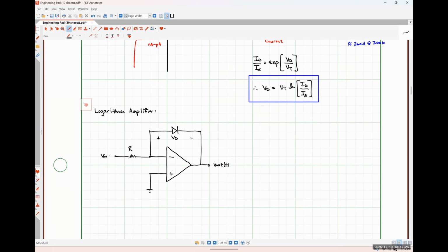Relays are inductors, and sometimes they will generate very, very large current or voltages if you turn them off really fast. So you put a flyback diode, so all the current will just go in a circle instead of busting up your circuit. Yeah, so it essentially gets converted into heat in that small loop instead of allowing that energy to burn out other things. Yeah.